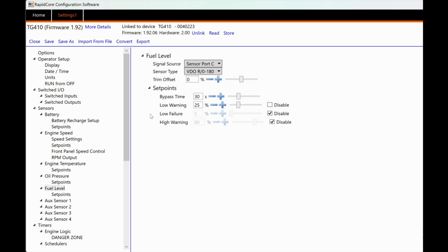If you use a fuel level sensor in your tank, it's handy to have the failure set to just before you run out of fuel. Many people prefer to have the engine shut off before it starts sucking in air, as this could make restarting it difficult. Therefore, having the engine deliberately shut off and display a low fuel warning is a useful feature. This allows the end user to simply refill the fuel tank and continue using the engine or generator without encountering any issues with air in the fuel lines.